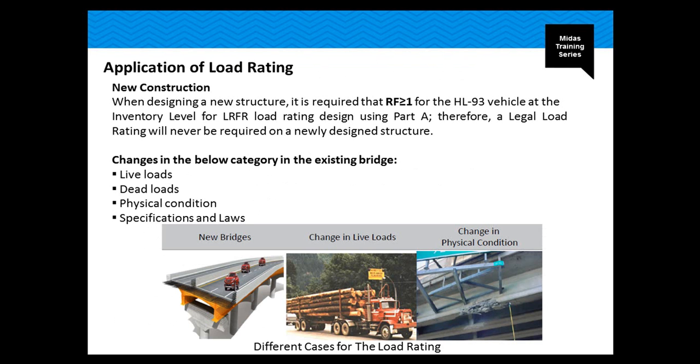In the application, when designing new structures, it is required that the rating factor is higher than 1 for the HL93 vehicle at the inventory level for LRFR load rating. Therefore, a legal load rating will be required on a newly designed structure.